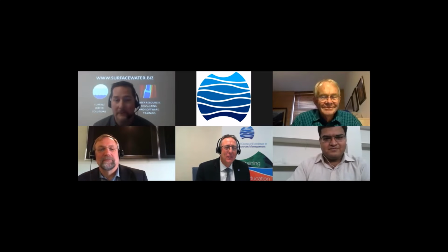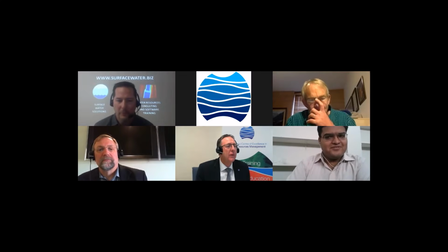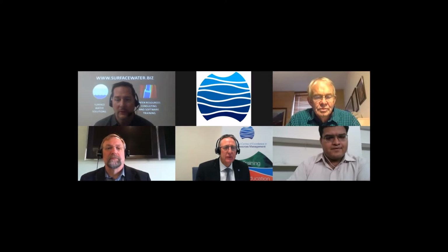What we would do if bathymetry is not available, you have to actually extract the bathymetry from your terrain data. And I've got an example in one of my workshops that I've just done, posted something on wormhole culverts on my website, where I've gone in and extracted some terrain from it. I've actually taken the bathymetry out. So you would need either manual readings, and you can do this with 1D cross sections. You can actually run a cross section from out in the delta and pull the water out of it by lowering your terrain. And it's a bit complex. Come to the class and you'll learn some more about it.